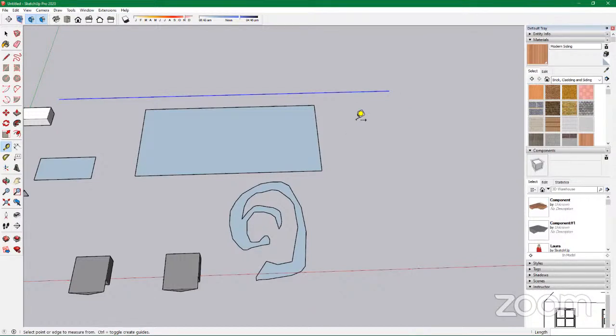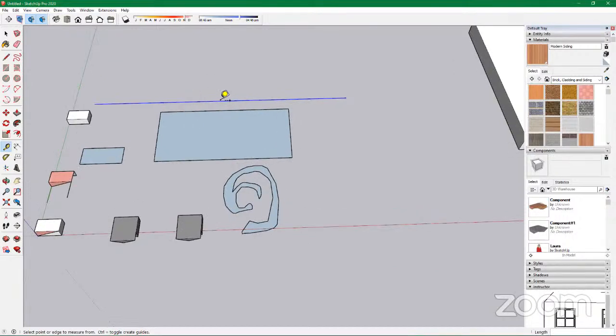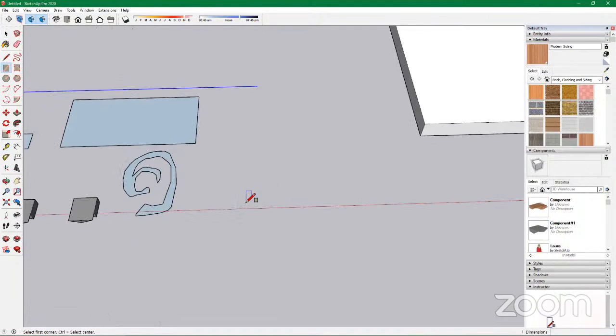Okay, I should explain the rectangle. Okay, now this is for the line. Now for the rectangle, if I pick my first point, like so, and then I just drag. If you look there, you see dimensions. Now for the dimensions, you see one of them is bigger and the other one is smaller. Sometimes it gets tricky, so this is the easiest way to identify it. So now the biggest side there is talking about the width, yeah, the x-axis, while the smaller side there is talking about the y-axis. Understood?